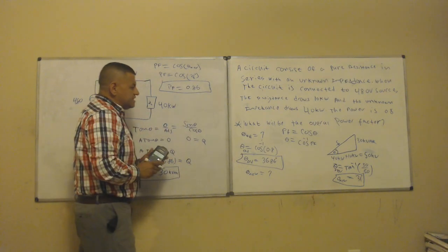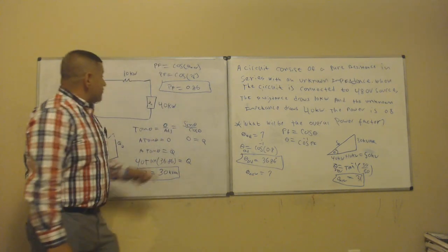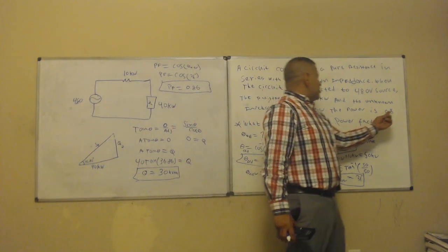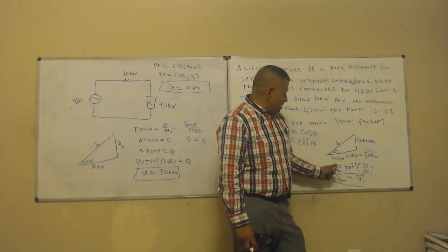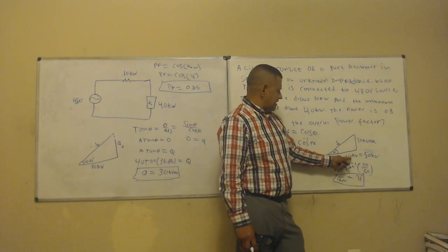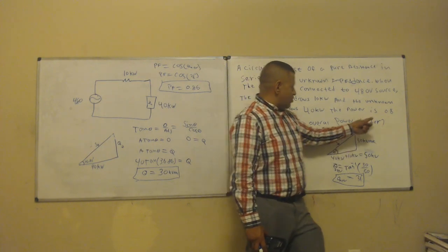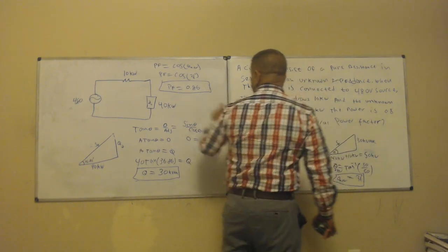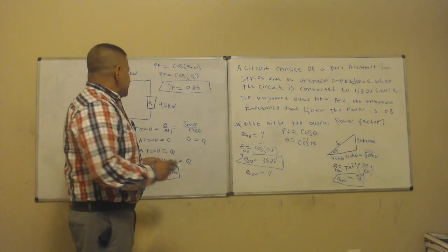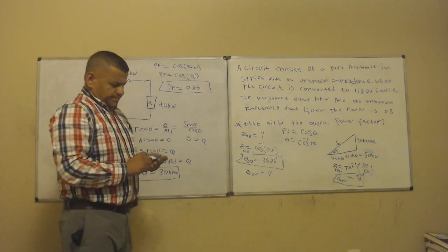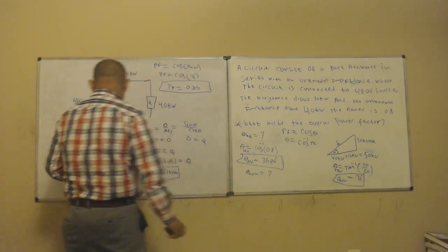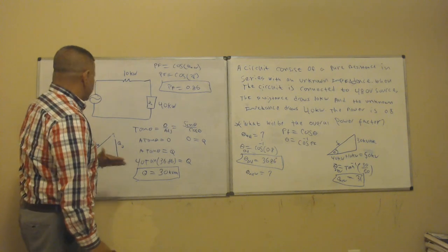And it makes sense because this power factor is higher than the one that we had, right? We had 0.8. And the reason why is because we incremented the real power by 10 kilowatts. You can see we incremented by 10 kilowatts. That's why we have a better power factor, 0.86. Okay, so that is the final answer for that problem. That was not bad, right? Good problems.